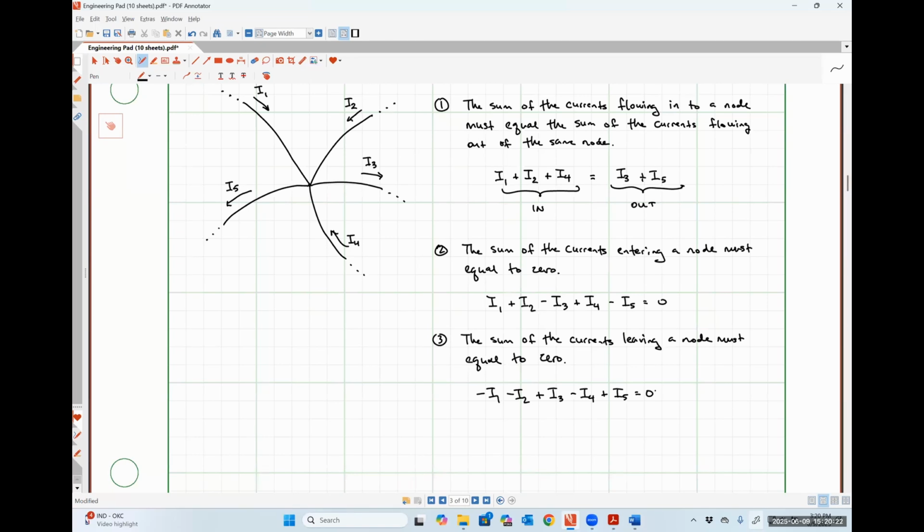which is the exact same thing as our relationship from formulation number 2, except that everything is multiplied by a factor of -1. And that should hopefully make sense to us, because we know that in order to change the direction on our currents, we simply multiply it by a factor of -1. So before we get into some examples here, does anybody have any questions or concerns about KCL?